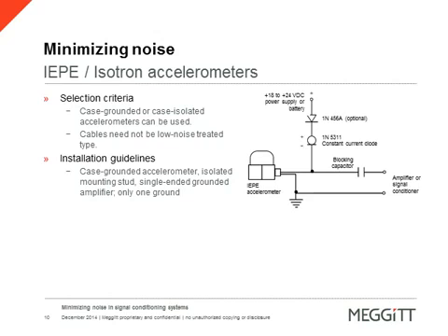Next is IEPE Isotron accelerometers. Most likely this is the most common accelerometer in use today. Again, Endevco offers case-grounded and case-isolated accelerometers. The cables for an IEPE or Isotron do not need to be low noise treated, but they can be used. It depends on the application, what you choose to use, what you have, or to use the lower cost non-low noise cables.